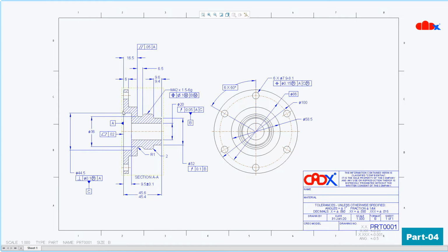So we can place it using either this surface or this surface, and that is why we can assign datum A to either this surface or this surface. In this case, I have assigned datum A to this surface because I am placing this surface on my inspection table. So let's understand that this line is your inspection table. You are placing this part on this table using this surface. The moment you place this part onto this surface, this directional movement is blocked. So one directional movement is fixed. Now this part can move either in this direction or in this direction, and that is why we assign the primary datum, datum A, to that surface.